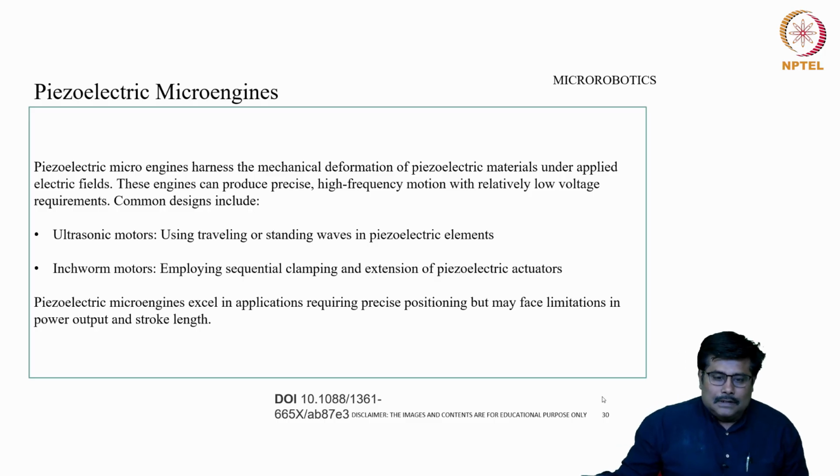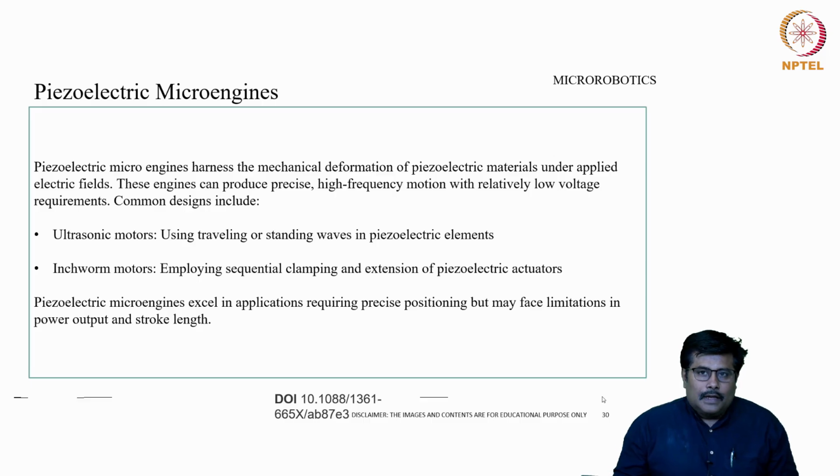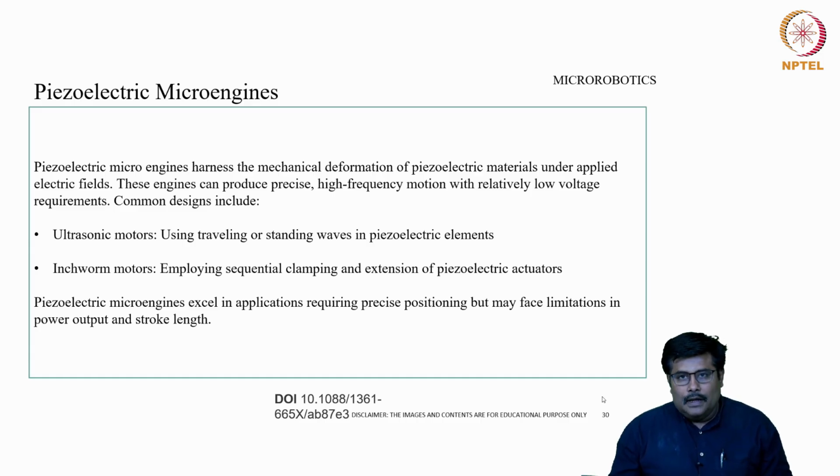In today's lecture, we will discuss one of the key aspects, which is called piezoelectric based micro engines. Piezoelectric micro engines harness the mechanical deformation of piezoelectric material under an applied electric field. These engines can produce precise, high frequency motion with relatively low voltage requirements.